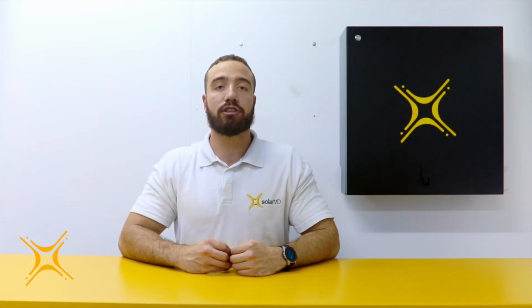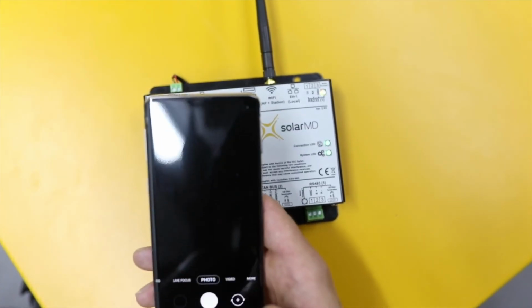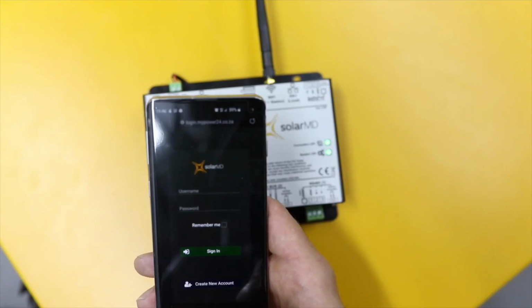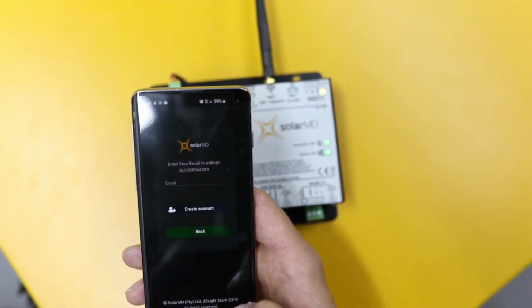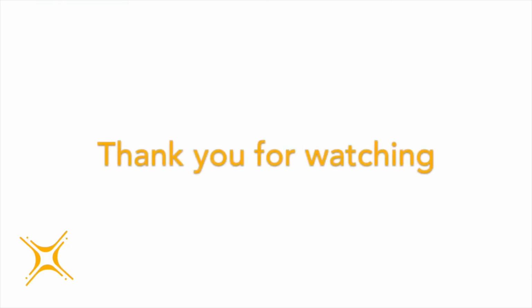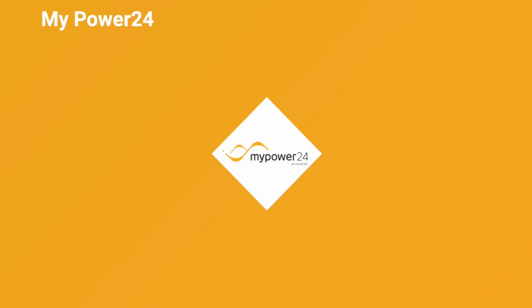Step 6. Device registration. To register your connected device, simply scan the QR code printed on your logger using your smartphone. This will take you to the MyPower24 login page. If you don't have an account, you can simply select the Create a New Account option and follow the easy procedure to register. If you are an existing user, you can just log in and the logger will be allocated to your account. That is how easy it is to connect the logger.